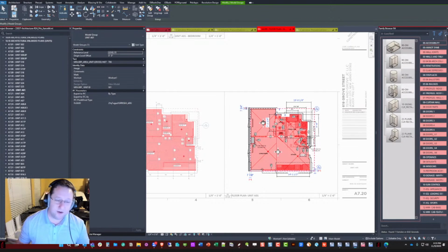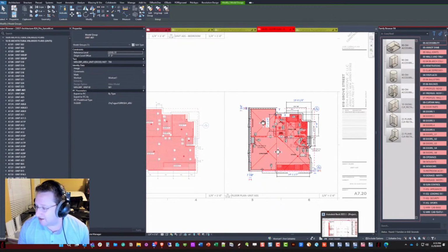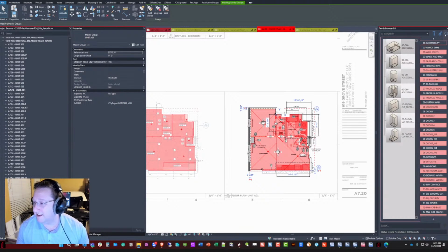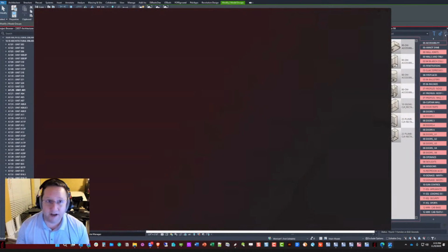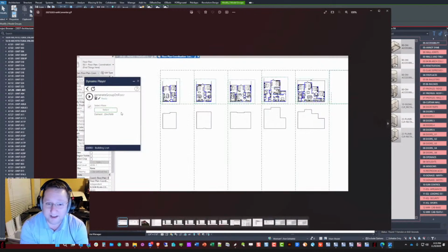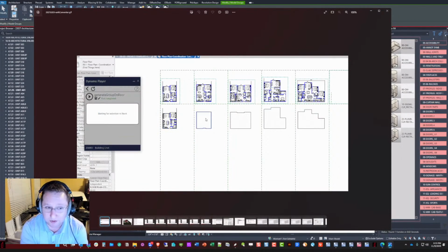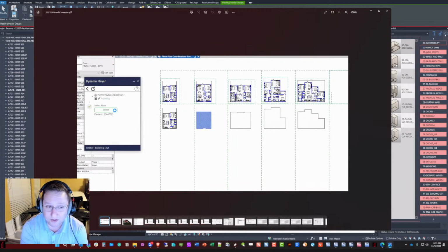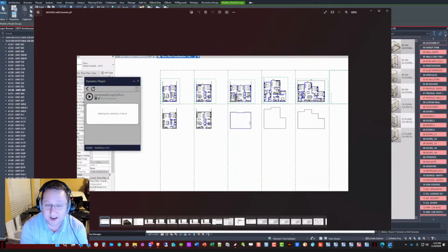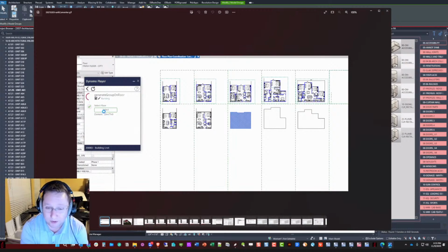We pulled it up yesterday, and I'll go off script and pull this up really quick. I'm going to just throw this out there that this was something that John Pearson put together for this specific reason. But basically, we were working with TestFit on an initiative for migrating stuff to Revit, and John came up with this wild workflow where you have a floor that matches the shape of the unit groups, and you can just design using the floors, and then when you're ready, you can run this Dynamo graph, and it will find the group that you've defined and swap the floor for it.